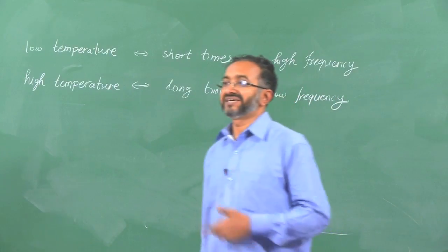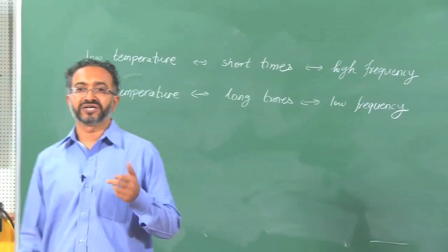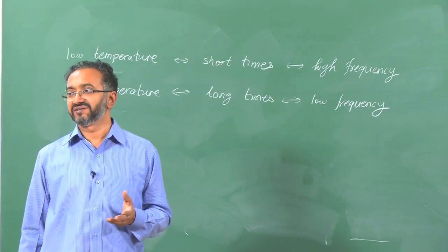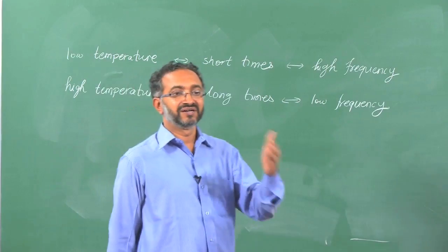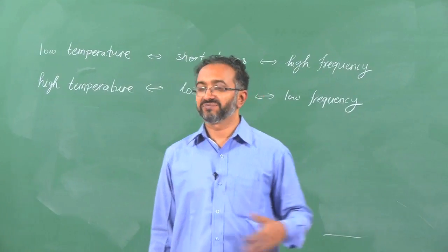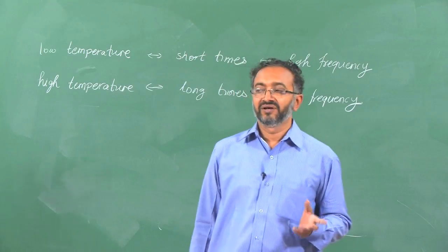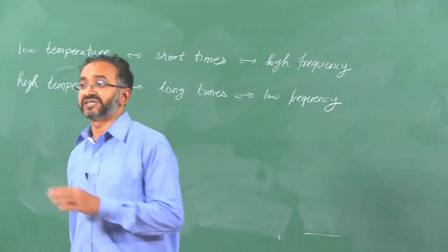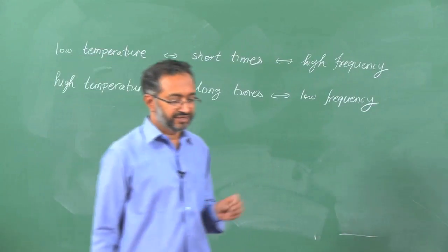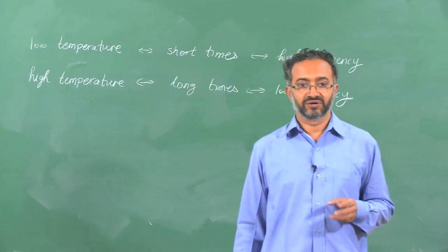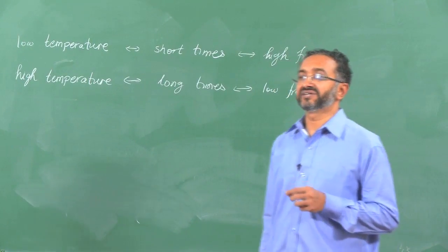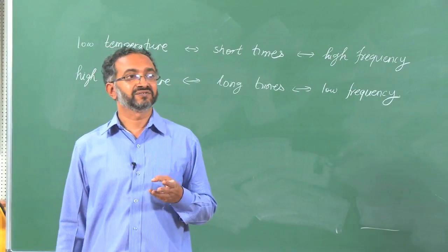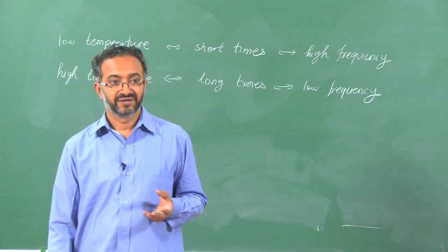So, whatever are the basic relaxation modes which depend, let us say, on bond rotation or reptation, all of these are basically Arrhenius time dependent. So, relaxation time decreases exponentially as a function of temperature based on the Arrhenius rate process. On the other hand, if you are closer to a rubbery material or closer to glass transition, then the WLF equation is what is observed. In this case, the relaxation time increases more rapidly than what Arrhenius would predict.